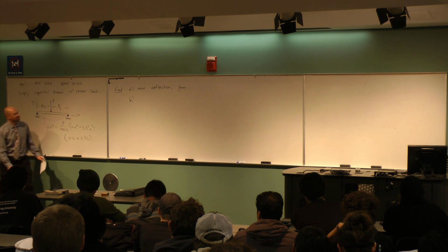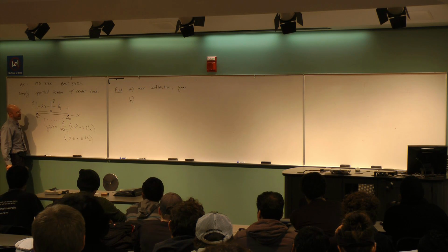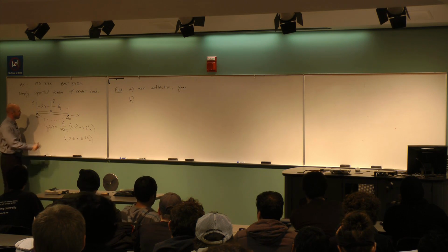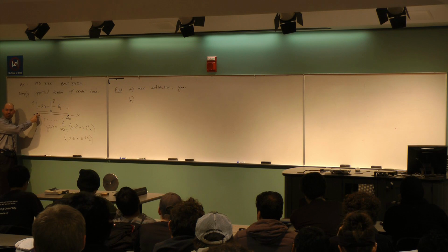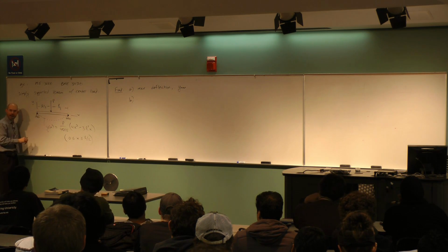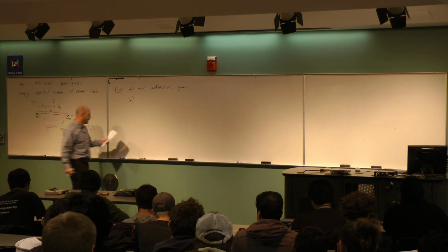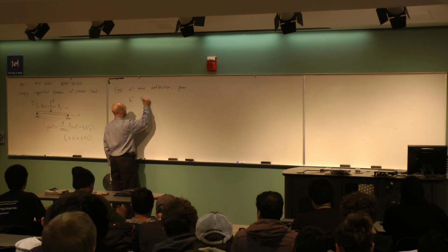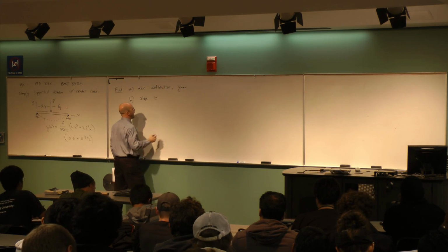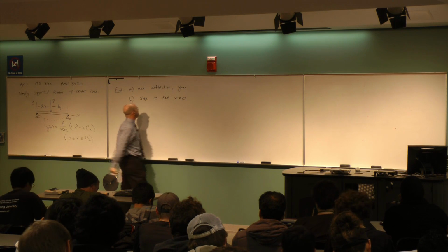So one of the things I'm interested in, besides just how much this thing deforms at the maximum location, is what's this angle over here at the bearing? Because if I try and do too much at the bearing here, I can damage the life of the bearings. So pretty practical kind of things. So for this reason, I might want to find the slope at the end, so for example, x equals 0.